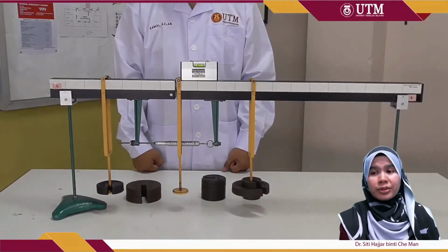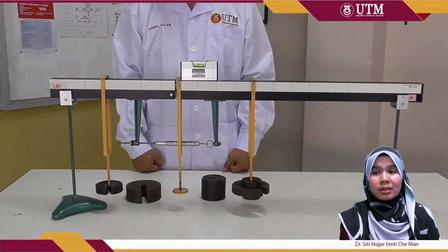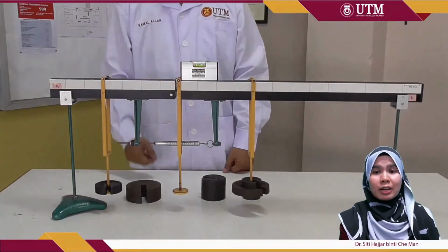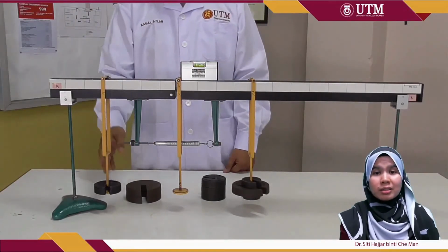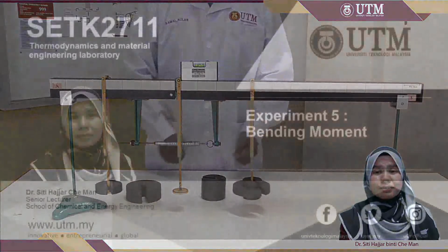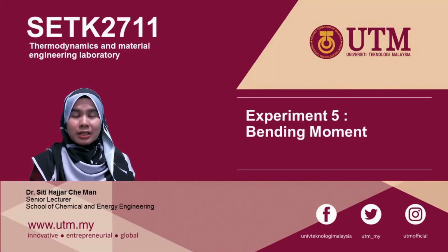In order to improve the accuracy of the experiment, you have to make sure the position of the eye is perpendicular to the spring balance, and always make sure the load hangers are at the right position each time applying the load. That's basically how to get the data points for this experiment.